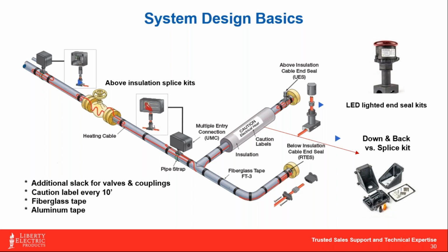You can access it. You can get in there with a multimeter. You can test to verify if that particular splice was the bad one, things like that. So, that part is critical. But oftentimes an extra 15 feet of heat cable is a much better investment versus trying to pull off an acceptable splice plus the splice box and everything that kind of goes into that.